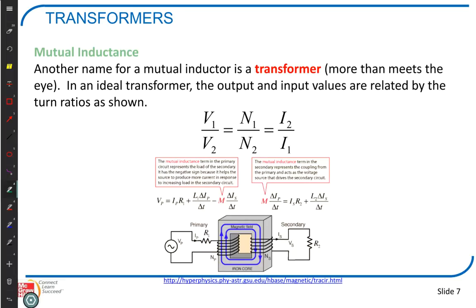Now, there is a downside. If I put a magnetic field on the iron, it causes those little domains inside to rotate. That's why it has its large permeability. But if I'm going to make something physically rotate, well, that took some energy, right? So there's work involved with making it rotate, so you do have some loss there.